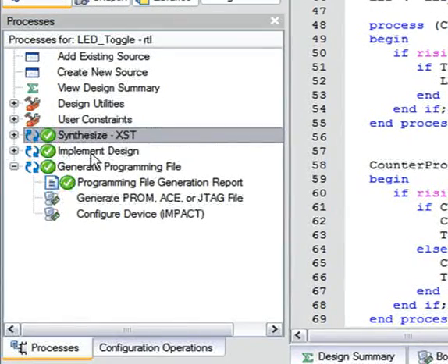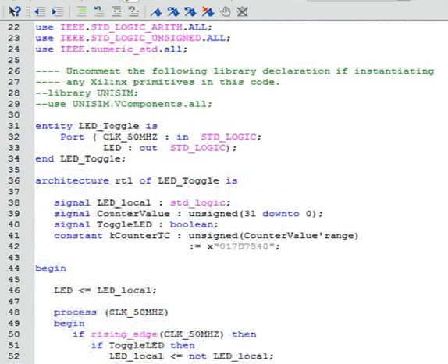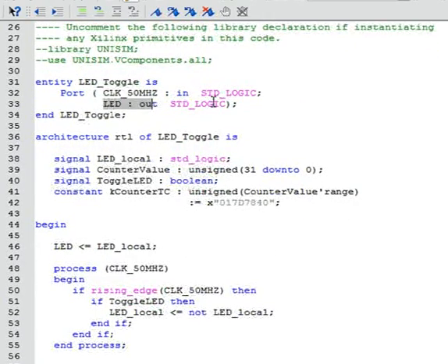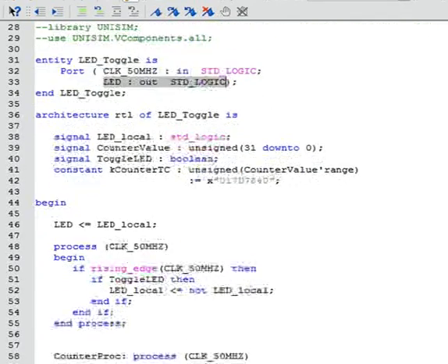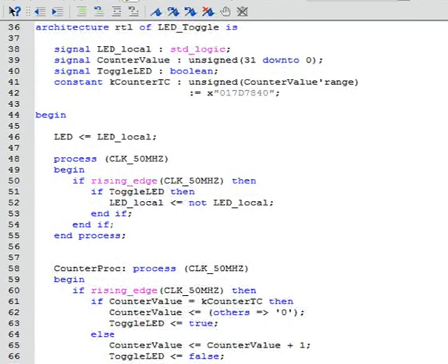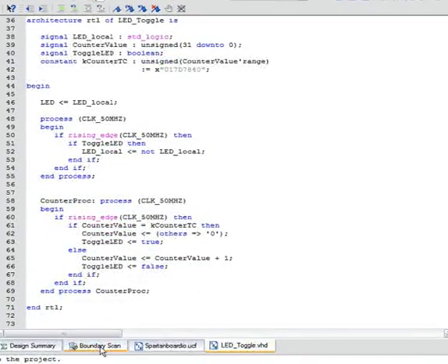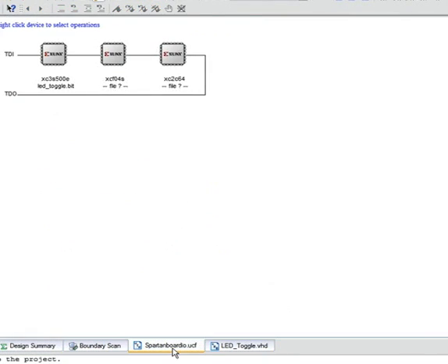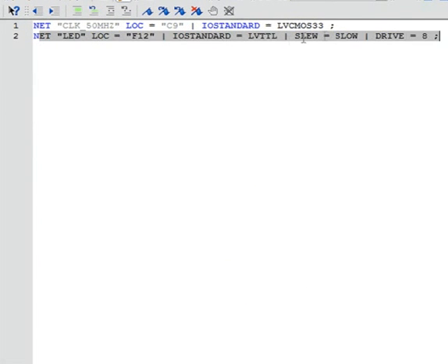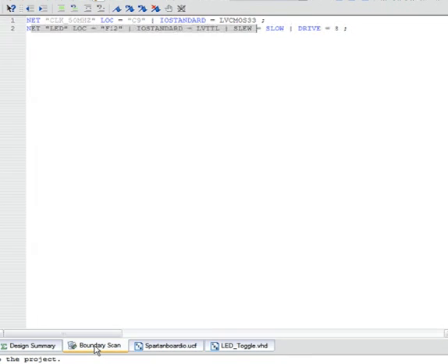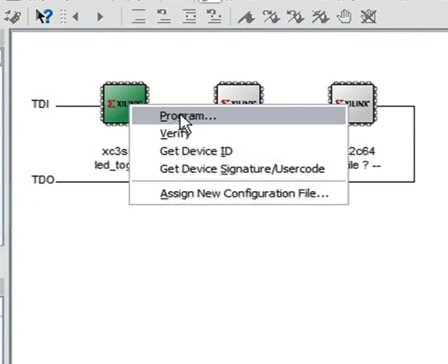But first, let's review. Using the Xilinx Webpack toolchain, let's build a very simple application that toggles an LED upon selection of a switch. In this application, you'll see that we define an LED. We then will use that local variable in a traditional loop to flash the LED upon the selection of a switch. At this point, let's tie the specific pin we wish to control that is connected to the LED within our application. Now we will compile and build our application.